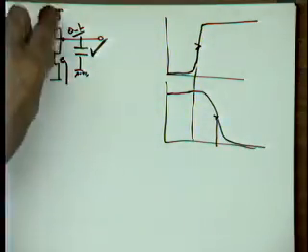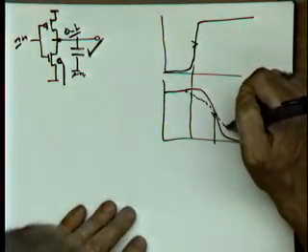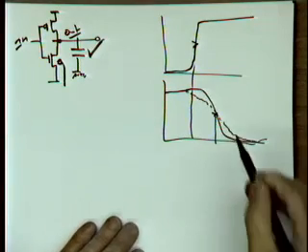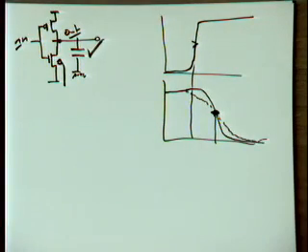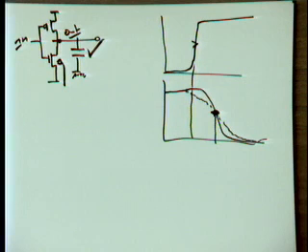We're going to replace my transistor by a linear element, which might be a little bit different in its curve. But at the 50% point, you get exactly the same value. Which is okay. I don't really care about what's happening in between. What I really care about is what's my propagation delay. So if I get a way of approximating that gate delay in the perfect way, I'm going to be in good shape. Okay? So that's what we're trying to do.